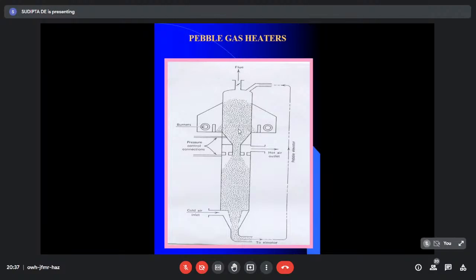Okay, so what are these things? As I'm repeatedly telling, I cannot go into more engineering in these issues, because the design of these particular pebbles can be a good MTech project, as can the design of the entire system, because there are issues. The air Reynolds number will be needed, I mean for the heat transfer coefficient. Based on that, we need the Prandtl number, and there are certain correlations available. But those mathematical relations I cannot use in this open elective class.